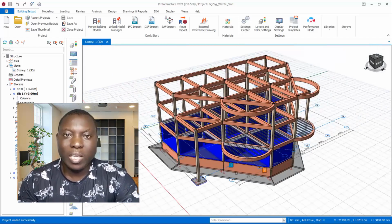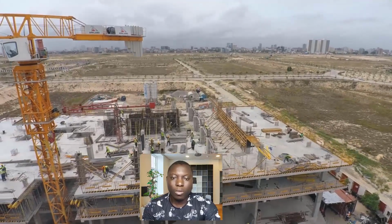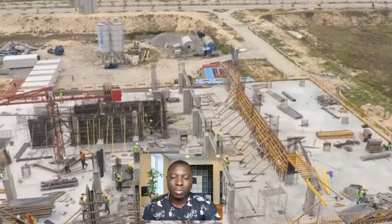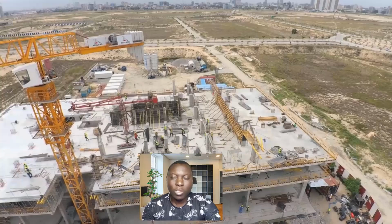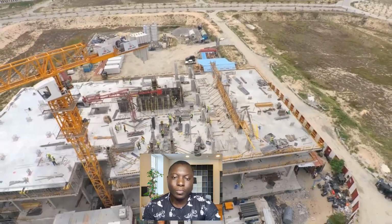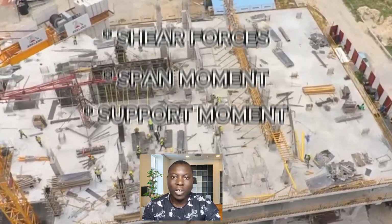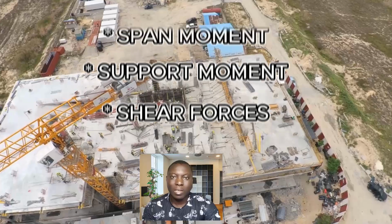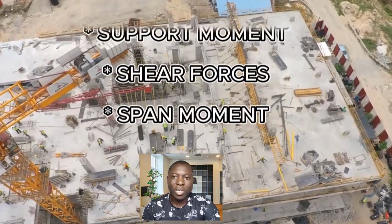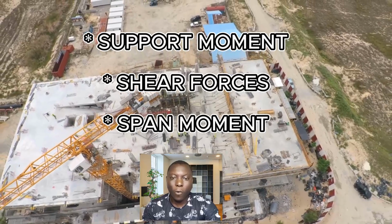I was opportune to design a shopping mall using a zigzag waffle slab, and as a structural engineer, when you are analyzing a zigzag waffle slab, you should expect to have the value for the support moment as well as the shear forces and the span moment. So this is what you are actually analyzing for.